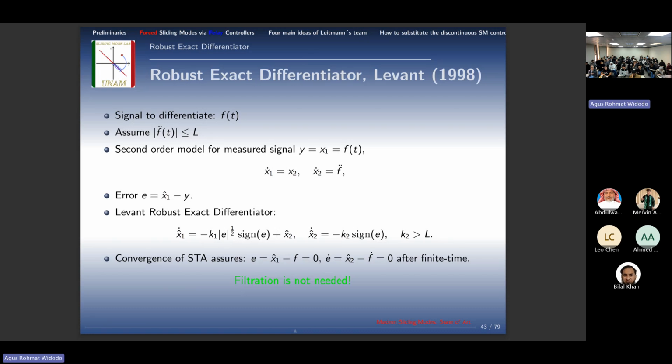So you will tell me, guy, you are using infinite gain here. Yes, I do. But what is proved? That it gives you the best possible approximation of the derivative in the presence of bounded noise. And it's mathematically proven by Kolmogorov in the 60s. And they proved that it is also the same here. That's it. So we've done the best possible differentiator, and on this base, we've constructed observers.